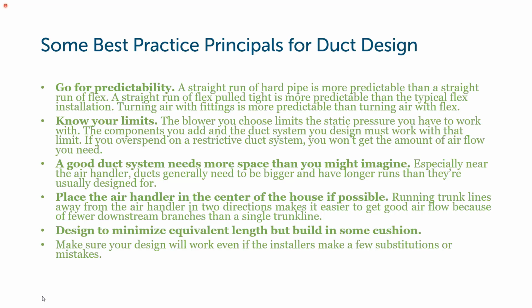So let's go for predictability here, try to get the system design and the duct layout understood before anybody starts digging a hole. These are just fundamental principles of good duct work and good duct design. One thing that comes into play here is oftentimes you need more space than you might think to get appropriate flows throughout a house. Trying to center the air handler within the building eases design and eases layout and performance.